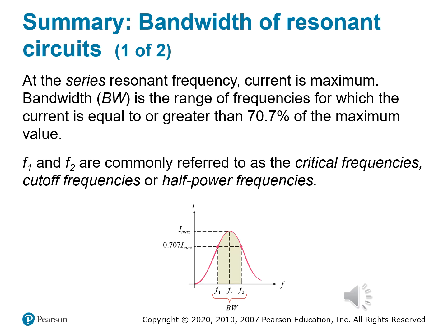It doesn't really matter. The radio's tuned into a specific frequency, but you're going to notice something. If you drift too far away from that sweet spot, the signal starts fading. That sweet spot in a series resonant circuit, that's where the current peaks. That's where you get maximum resonance. It's that golden frequency, f sub R, where everything's aligned and the circuit impedance is at a minimum. But there's a kicker to this. The real magic happens in the zone around that peak, and that's what we call the bandwidth, denoted by BW.